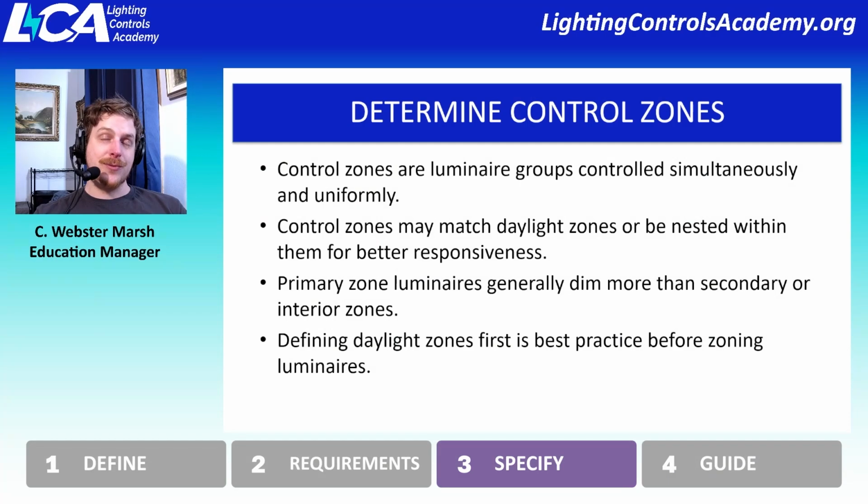And while I don't necessarily recommend that you have a linear fixture that spans the entire length of the space and gets cut up that way, it happens, and the way that you address that is going to be how granular you want that adjustment to look, because the contribution from that fixture is still going to be dramatically impacted by how much daylight contribution you have, and energy code requires that you still split that fixture up.